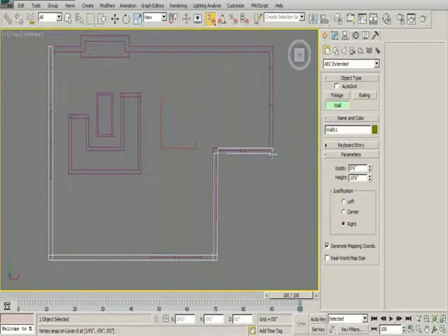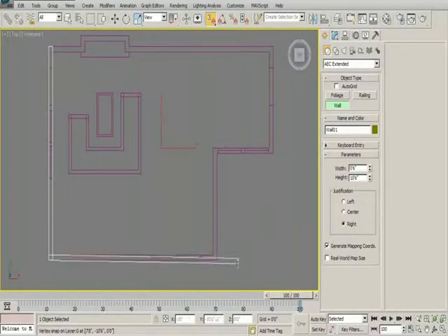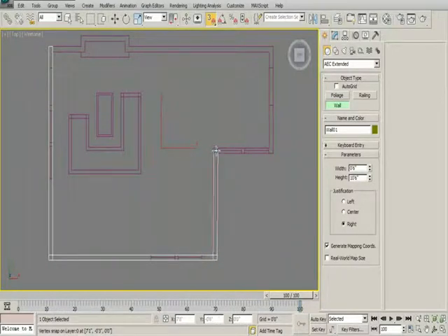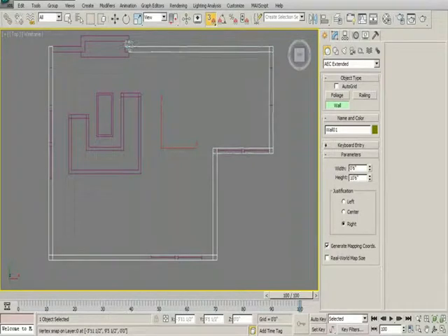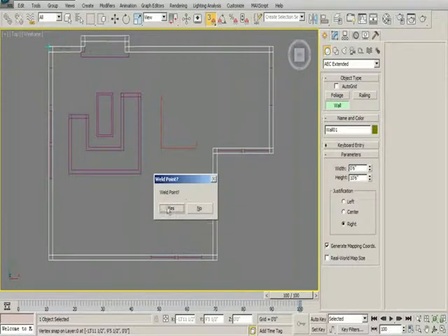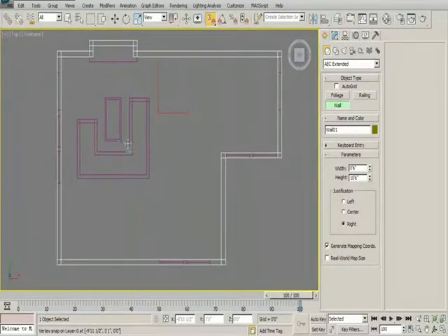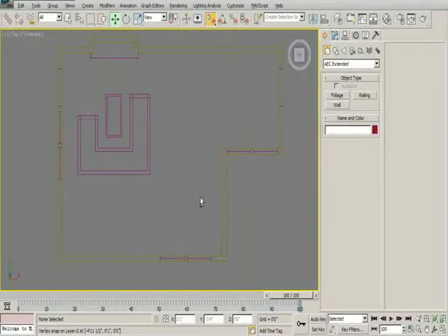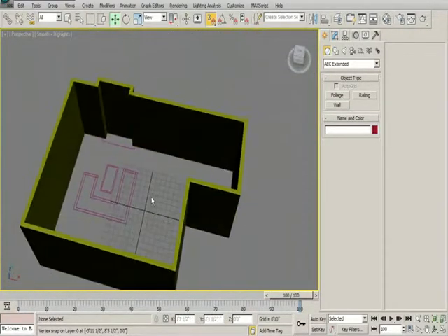Quickly create a wall. Okay, I did wrong here. It's not a straight wall. So press backspace to go backward. You can see it removed one step for me. Weld point is yes, we want to weld. Okay, right click to end the current selection. So now our wall is ready.